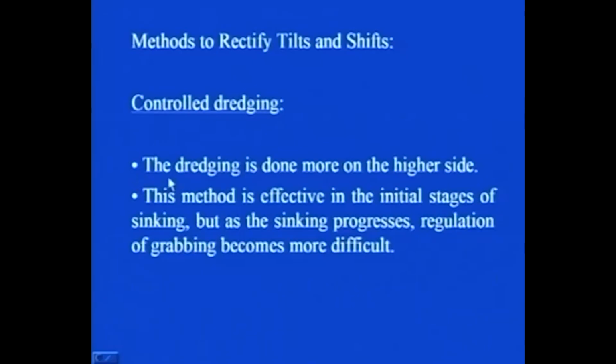One is controlled dredging. In this one, the dredging is done more on the higher side. This method is effective in the initial stages of sinking, but as the sinking progresses, regulation of grabbing becomes more difficult. So if in the initial stage of sinking you observe tilts, then you can adopt controlled dredging to rectify tilts and shifts.